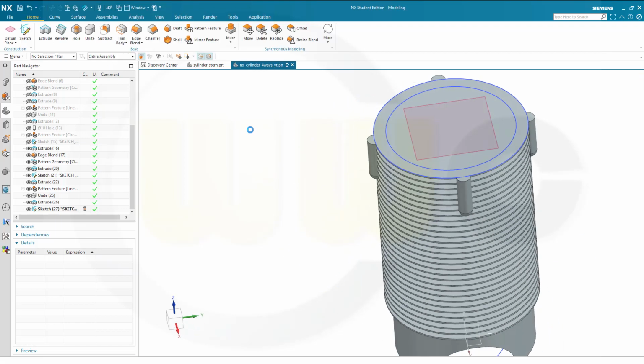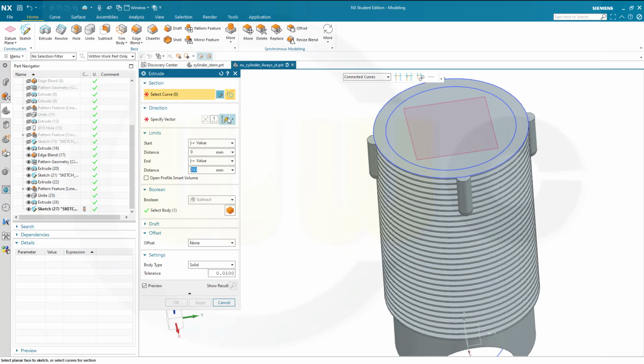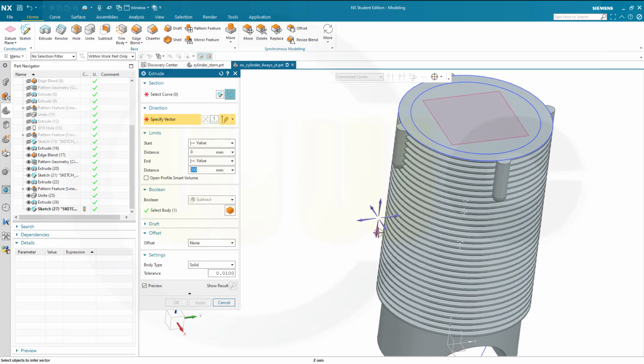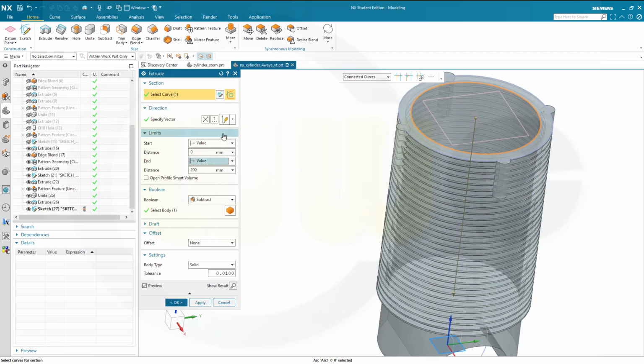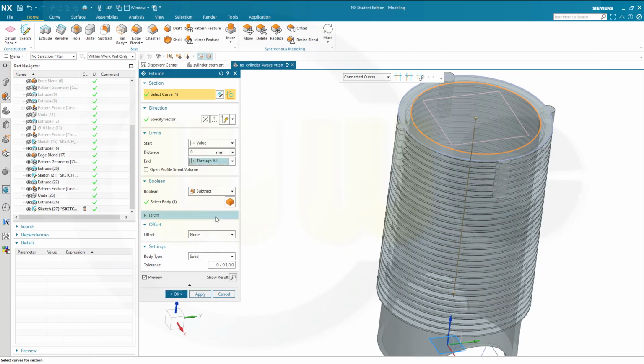Finish that sketch, and let's make an extrude. Direction would be this one here, and it could go from start to limit. Select the curve would be helpful, like that, and this could go through all, for example. This looks okay, and confirm.